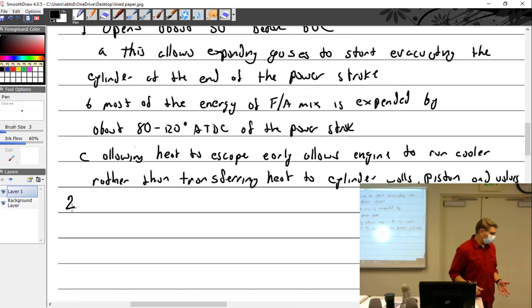Of course, now I did say that what cools the exhaust valve is being on its seat. Here we have a cutaway, and you can see the valve sitting there, and its little seat's right there. And that seat, of course, touches the valve, and then the seat is connected to the cylinder head. The cylinder head is connected to the cooling fins, and that's where it cools. This is the intake, by the way. It doesn't matter, but same thing on the other side. Just so you know, you can always tell the intake versus the exhaust side of any cylinder. Exhaust side has more fins because it's hotter on that side. This has no fins right here because it's cold air coming.